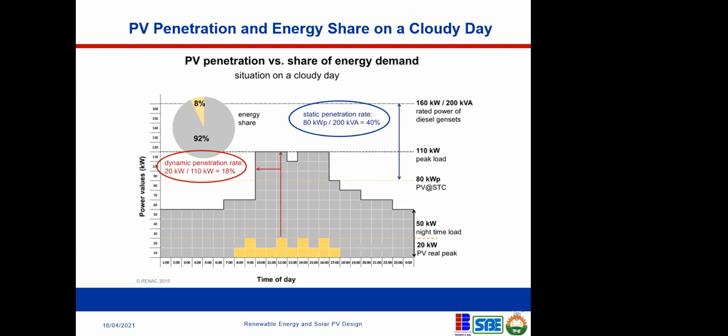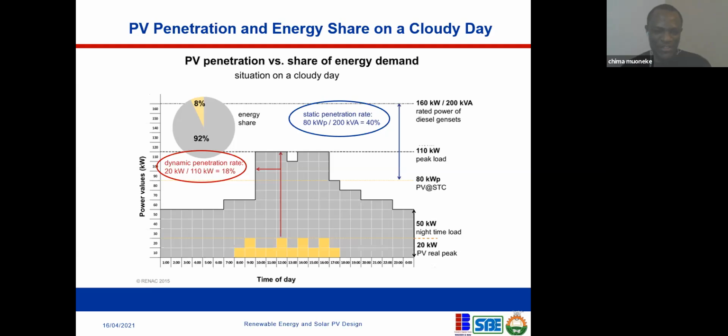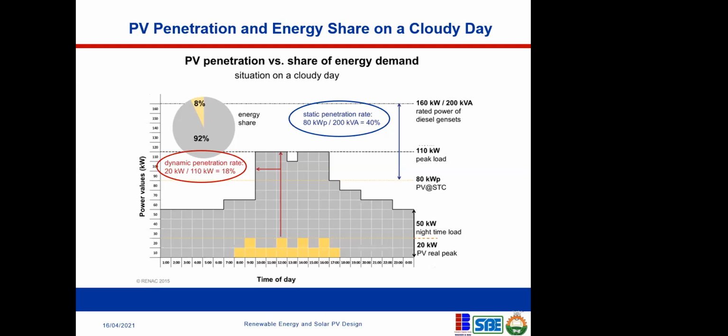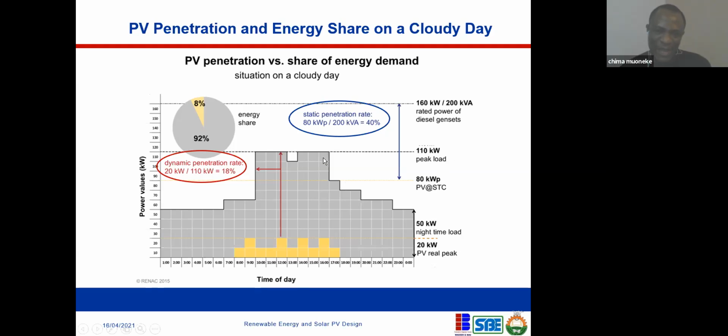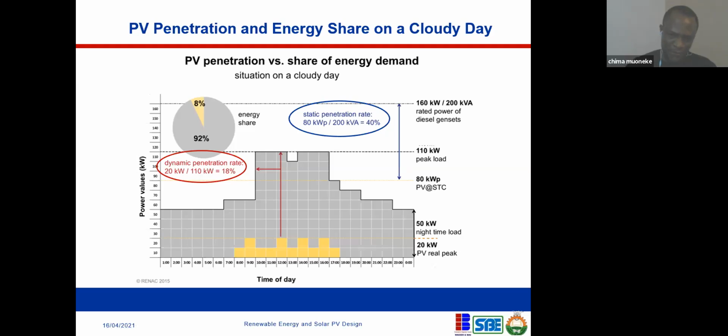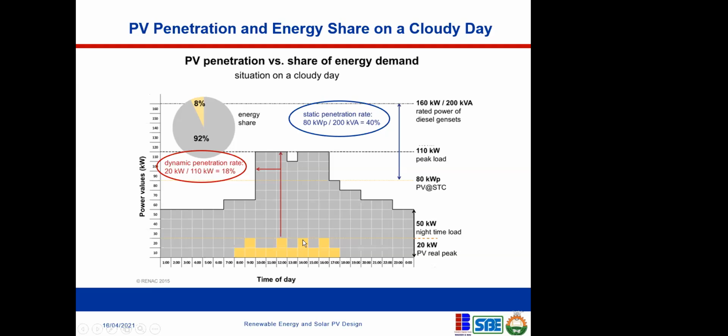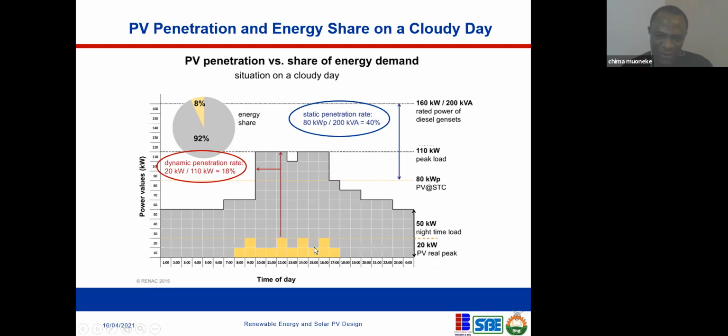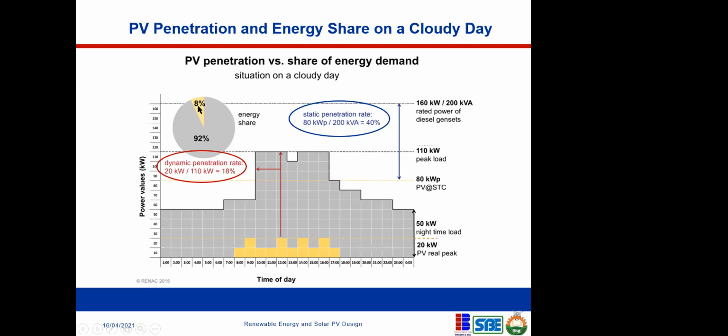Which is 110, right? No, 110 is your power, your demand, not your energy. So your energy is, I said that every one of these boxes represents 1 kilowatt hour. If you count all of these boxes, inclusive of the yellow ones, and you divide the number of boxes in yellow by the total number of boxes you have here, you will get 8%. 8%. Yes.